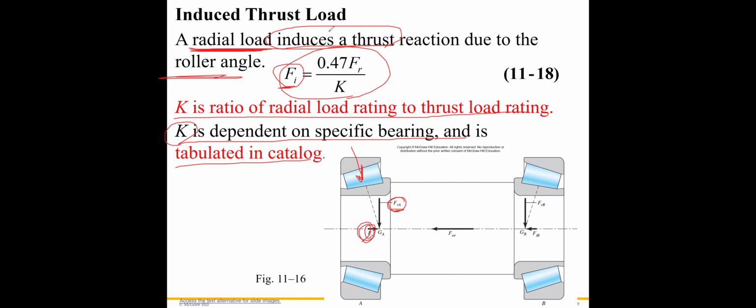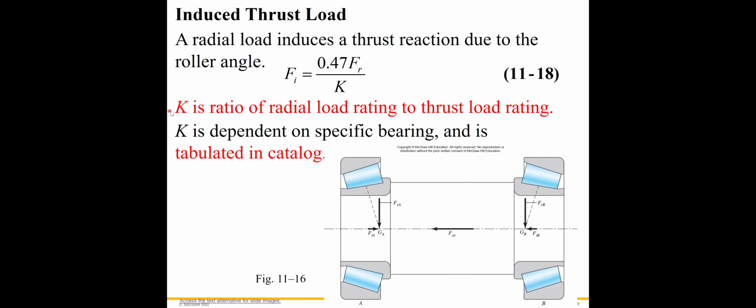I'm going to show you how to calculate this axial loading, including the induced axial load, induced thrust, and the external axial load. So the FAE, the E means the external axial load, and the induced axial load.